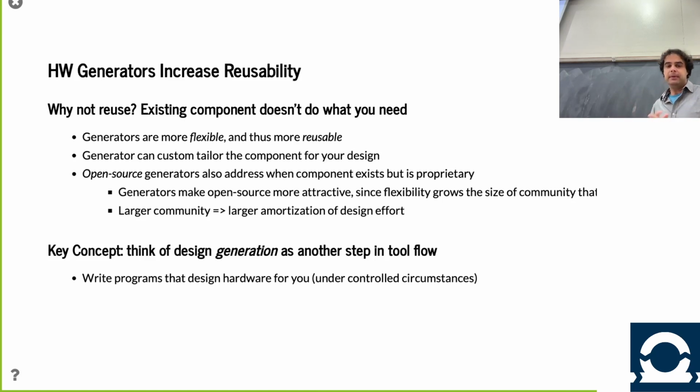So the key point behind these generators: really think of design generation as another step in the tool flow, right? Right now in the tool flow, I give the RTL to the synthesis tool, et cetera. Now, before RTL there's going to be this design generation step, right? Really we're writing programs that in turn are doing the hardware design for us. And it's not doing arbitrary, whatever stuff. It's controlled. It's under very specific plans, but that flexibility will be really helpful.